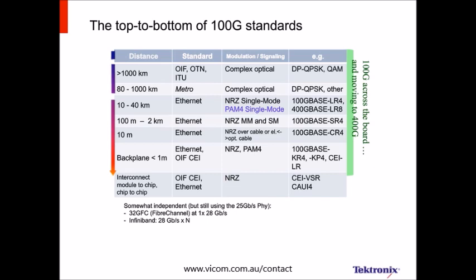But I just wanted to point out before we shift our focus entirely to Coherent, that even in the Ethernet world, we're seeing multi-level modulation now become important as they move to 400G. So I listed one example that we're seeing emerge from the 400 gig Ethernet working group that involves 8 wavelengths and using a PAM4 modulation. So today we see this convergence to 100 gig across the board, as Stephen mentioned at the top, but now, of course, moving to 400 gig.